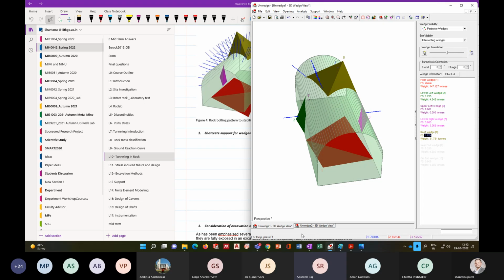Sir, also from Phase 2 we will get some configuration for this rock bolt. So sir, what to choose between the two? Like this full Phase 2 or this? What you are going to do is, first you get the support from your Q classification system, then you check it using this FEM analysis.